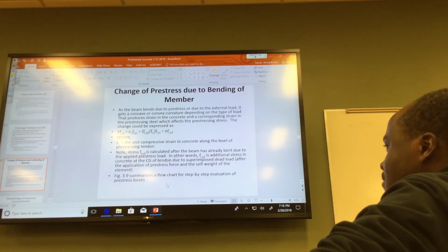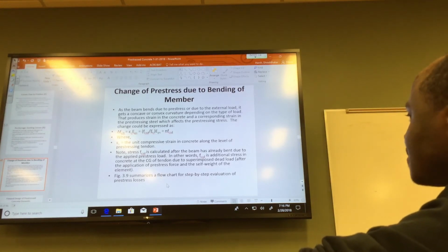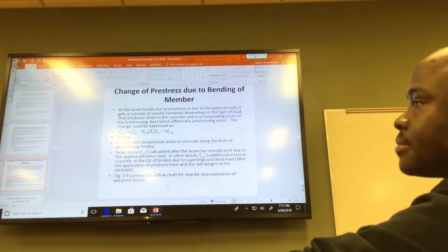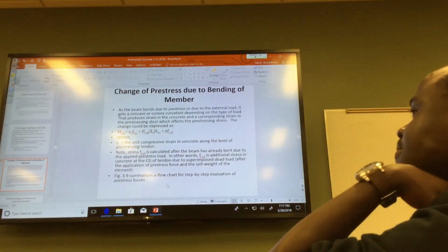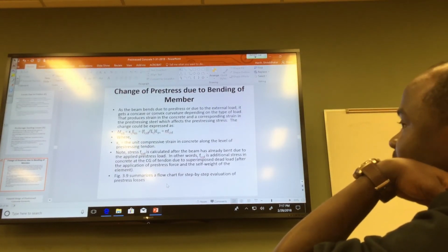But when you say live load, many times you use loads that are not quite transient when they are still called live load. So the right vocabulary should be sustained load and transient load, not live and dead. For example, this classroom, the furniture is a live load. Why is it live load? Because it moves around. Sometimes you have more furniture. In a couple of years, this may be something else, right?